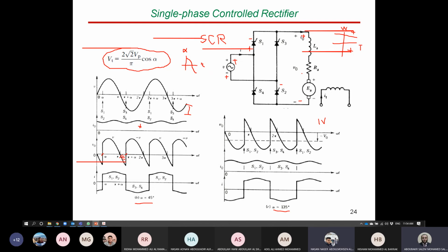Okay. Doctor, please. In all types, and at all times, if the power is negative, is it returned to the supply? Yes, the meaning of negative power is that the power flow is reversed. So instead of power flowing from electrical to mechanical, it now flows from mechanical to electrical, which means the power will be returned to the supply. The value of the power is the magnitude, but the sign is the direction of power flow. Okay.